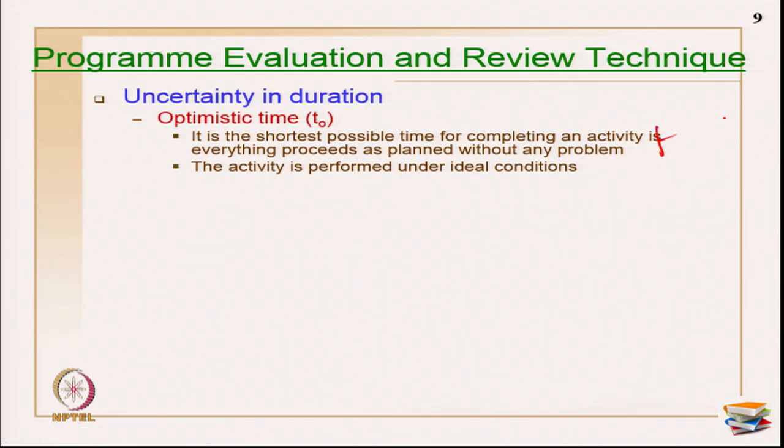Okay. So, if everything proceeds as planned without any problem, and the activity is performed under ideal conditions, with no breakdowns, no delays, no waiting for anything, engineers come, laborers come, everything starts in time. Such a short time for completing an activity, we call it the optimistic time.